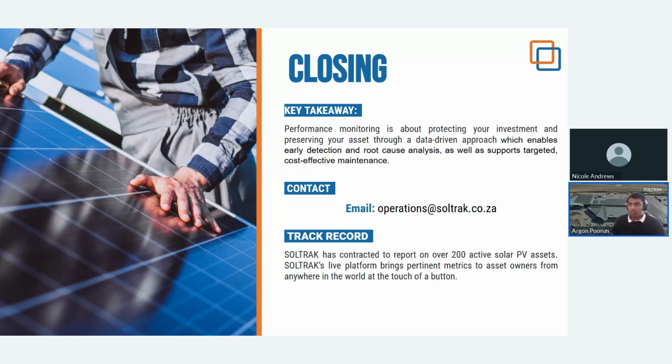So I would say it's considered within the financial performance, but when it comes to the energy performance, so whether the site is performing as it should be, it's probably best to stick to the kilowatt-hour impact. So the kilowatt hours produced versus what was guaranteed, and then essentially you're using the blended rate to understand what the value of that surplus or deficit was.